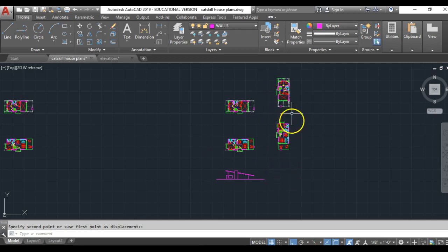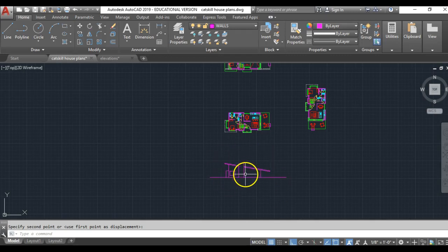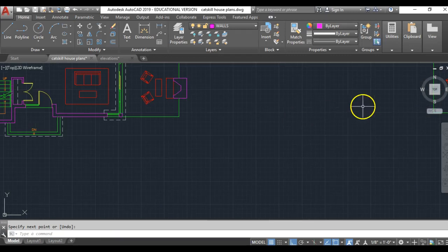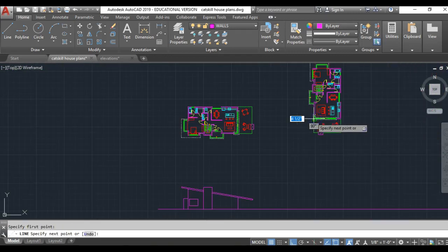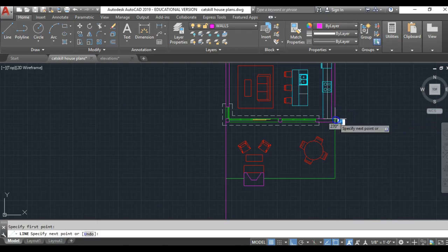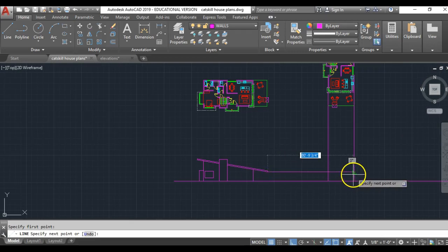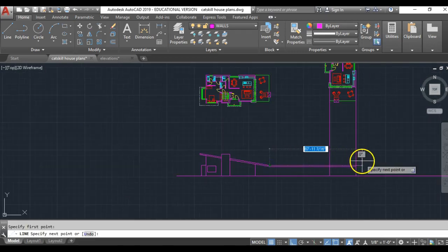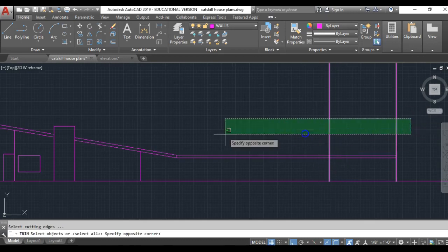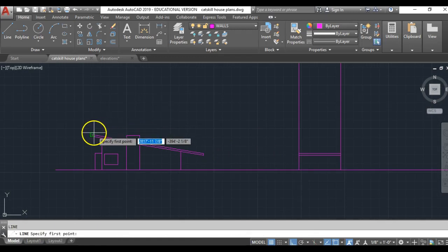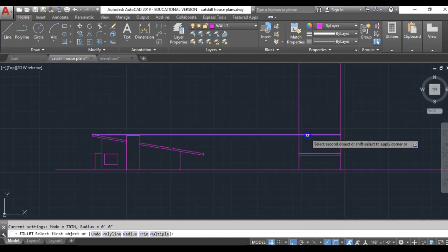And so now as I start the side elevation of this house, I'm going to continue to draw down as needed, but I can also draw across because I've set up a lot of geometry over in this elevation. I want all my elevations ultimately to be aligned to the right. So, as an example, I might continue the ground plane across. I might draw down like I did before from here to here and here to here, so that's the sides of the house. But I also know where the roof line is. I already have that figured out from the last drawing. So I'm going to come here and draw the bottom. You see the edge of the roof in this orientation, as well as, way back in the distance, the top of the roof back there.